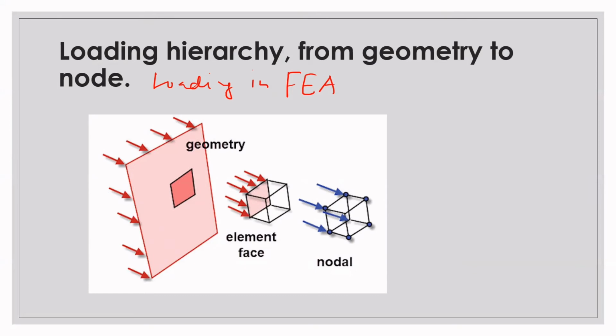As we can see, in most cases we will be applying a load to geometric entities such as surfaces and solid faces. And functionality in the preprocessor allows nodes present in the mesh to be associated with the geometric surface or face. And if we re-mesh to achieve a finer mesh, for example, the old nodes are deleted, but the new nodes are associated with the surface or face, and hence with any loading that is applied.